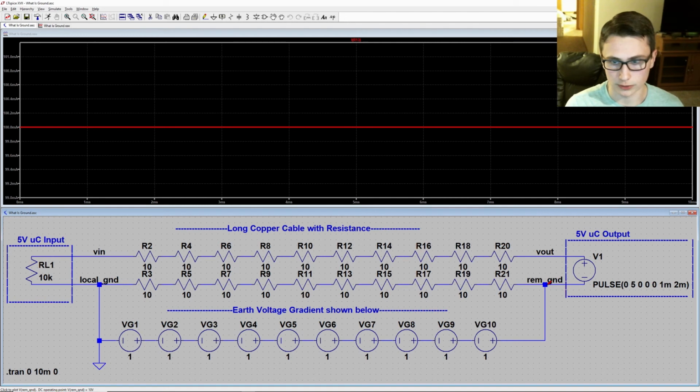Say these two systems were intentionally designed to use 2 different return potentials, or it's difficult to not say ground because I'm so used to it, but whatever their voltage reference point was, if one intentionally used 100 volts instead of 0 with respect to earth ground, this issue would be systematic when trying to connect different systems from different vendors. To avoid that, we all just decided that the ground underneath our feet should be ground.